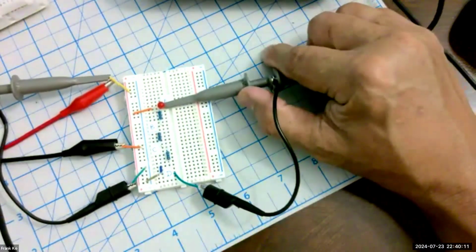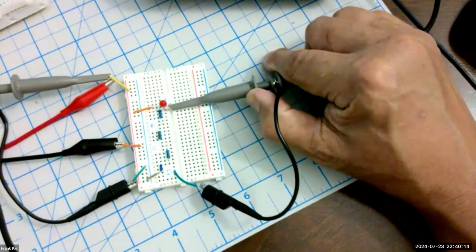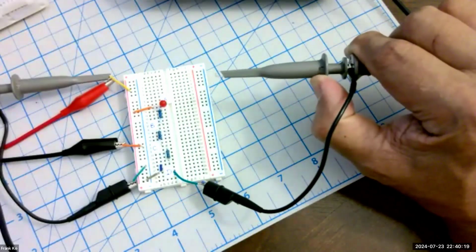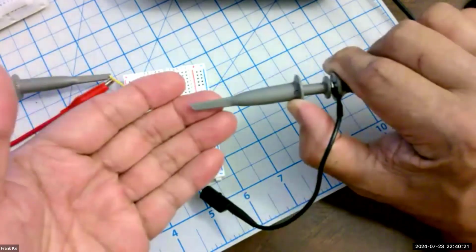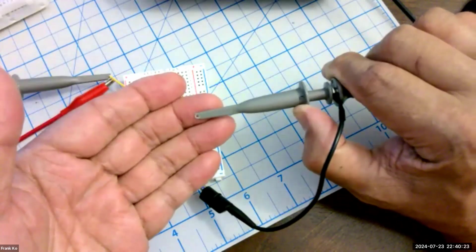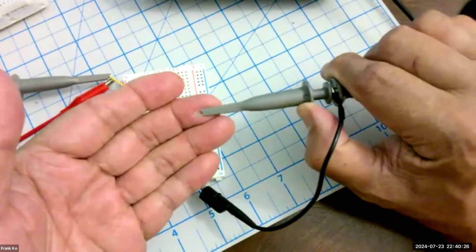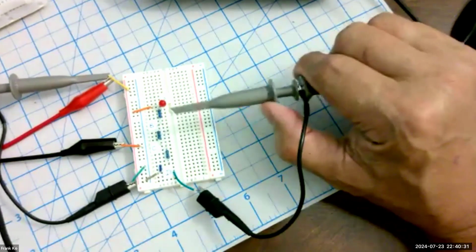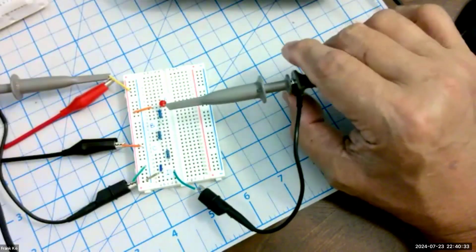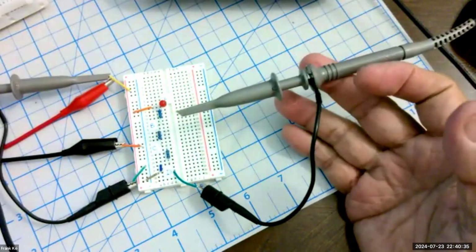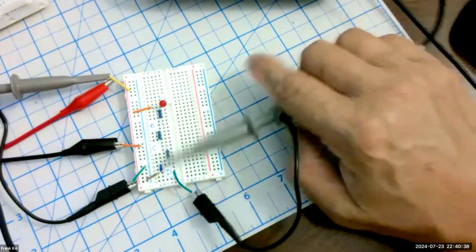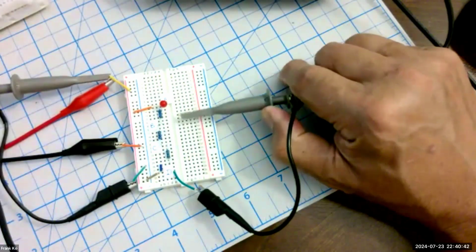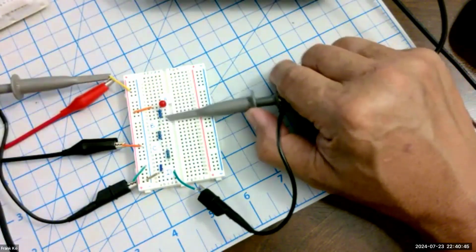The other end of the oscilloscope probe is a hook. So there's a hook right there. Let me do this so you can see the hook come out. Here, see the hook come out. There it is. There's the hook, simply by squeezing this way. And what I found convenient to use, because the spring is rather strong in any of these probes, and there's a fair amount of weight to the probe itself, I like using push pins as my point markers for making connections. So I'll make the connection right there.